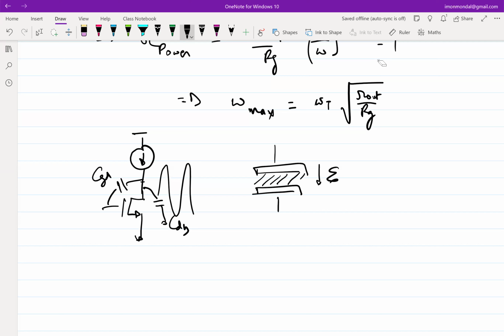It's basically the overlap capacitance between the gate and the drain. But the CDB capacitance is what type of capacitance? It's a junction capacitance, a reverse bias PN junction capacitance. So in a shallowly doped reverse bias PN junction capacitance versus this TOX, which one do you think is thinner? TOX is obviously thinner, right? So which one tends to break first? CGD typically tends to break first, right?